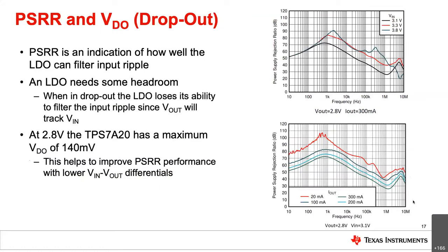While this may be true, it's actually more the essence of Ohm's law, where voltage is equal to resistance times the current. In this case, the dropout is equal to the RDS(on) of the pass FET times the output current. Another word that could be used here is actually headroom. So LDOs require a certain amount of dropout voltage in order to perform optimally. We refer to this optimal dropout as headroom, and usually it can be seen in our test conditions in the sense of the optimal dropout between the input and the output voltage.